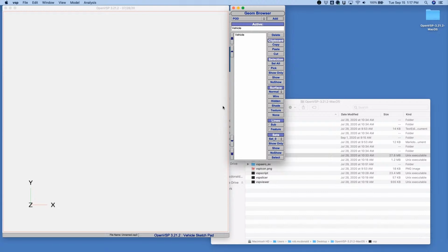What I would do is just use the design file, like that example I showed earlier. It's just 4 printf lines, so you'd have your MATLAB script with 4 lines of printf, dump out that file with whatever values you want for the variables, save that file, and then you can execute VSP using the system command to run an external program. And so that's probably how I would do it from MATLAB.